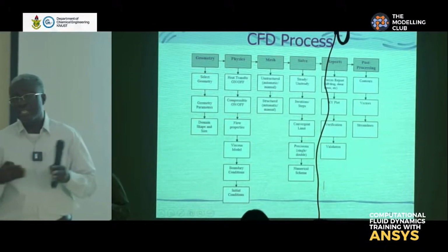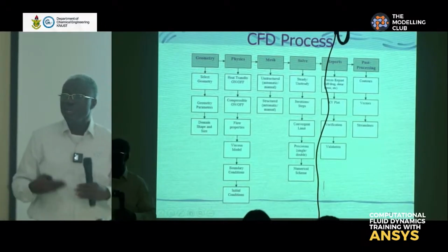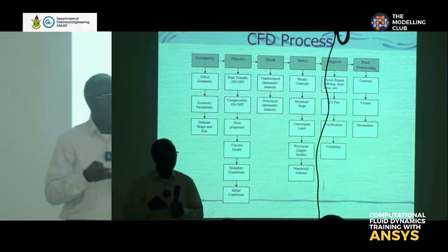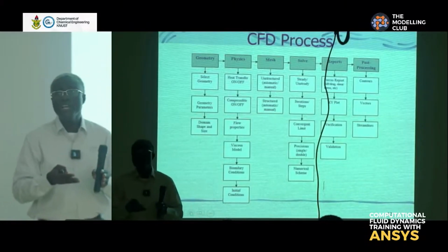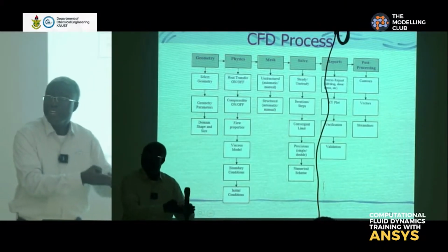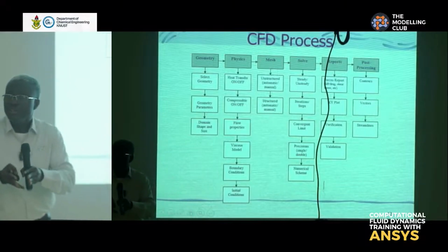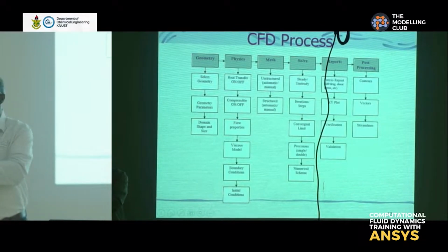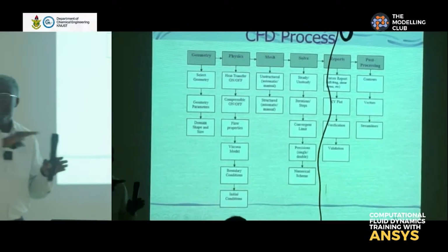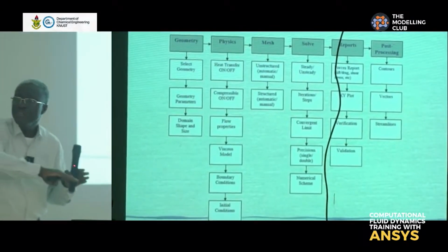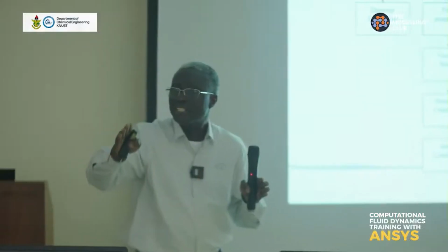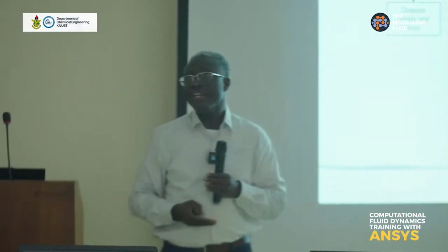Okay, so what I ask my students to do will be to do a grid optimization. First, do the experiment or the simulation with a coarse grid, a medium coarse, and a fine mesh. Let's see the results of these 3 cases. If it converges, if you see that as you keep reducing the grids, it is converging, then you know that you are in the right direction.